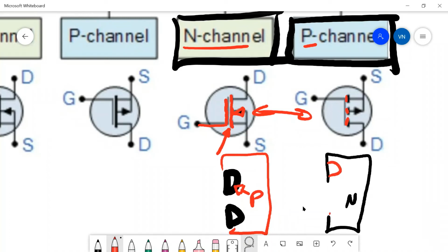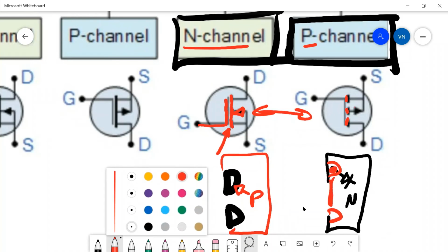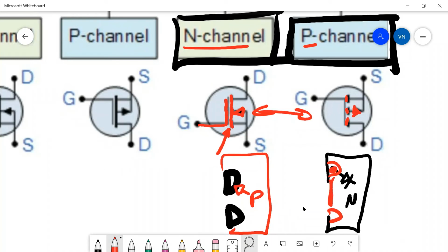there's 2 P channels in it, and then you're going to create a full P channel between the 2 P types. So in this one, the diode that normally sits inside the part is a diode between the P type here and the N type over here, so that diode points away from the gate. So the diode arrow within the part is telling you which way the internal diode created between the terminals and the body of the part.